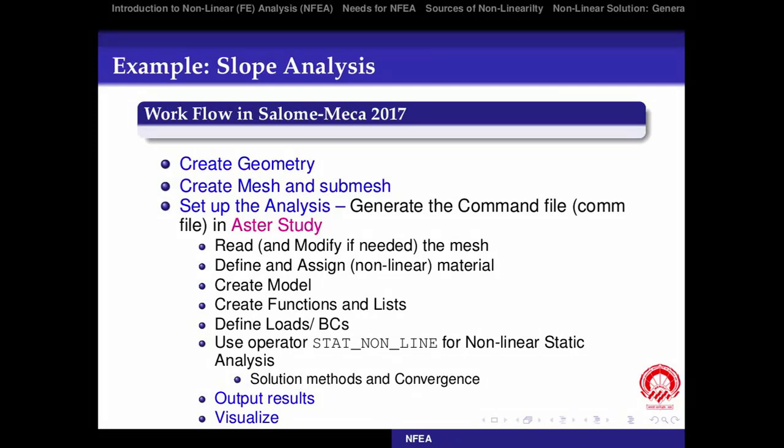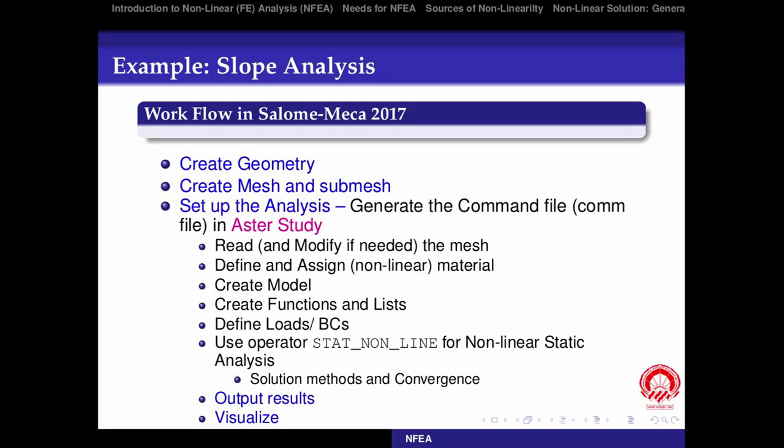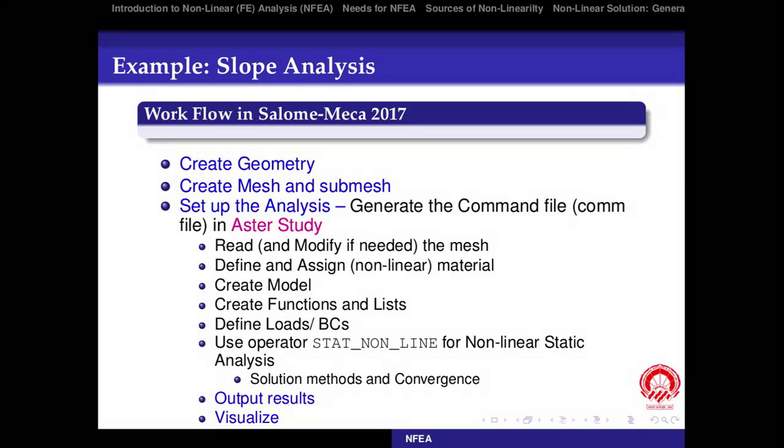But before visualizing, we need to output the results. We need to save the results in the form of some file. There can be two types of file. One may be a tabular file, a text file, or there can be a med file, which is a binary file that can be used for visualization directly.